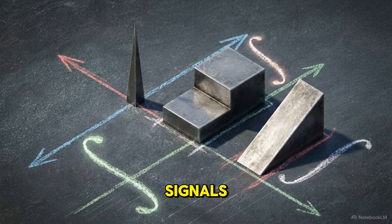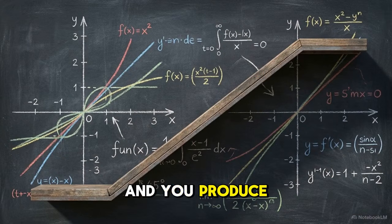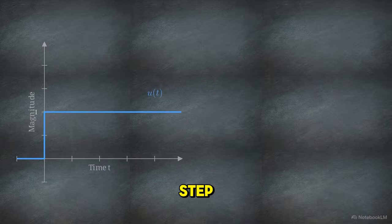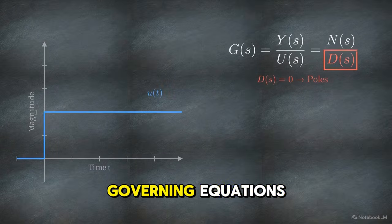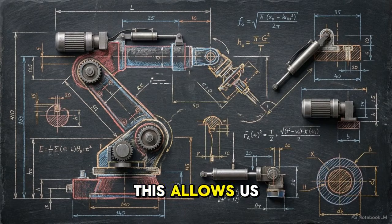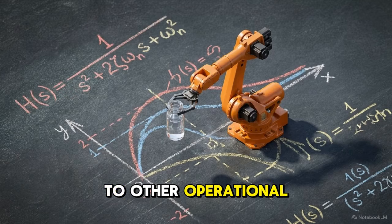These three test signals form a unified diagnostic suite tied together by calculus. Integrate an impulse and you get a step. Integrate the step and you produce a ramp. By analyzing how a system reacts to this sudden step, we can begin to derive the governing equations and root locations that dictate its performance. This allows us to build a model that predicts how that same system will respond to other operational demands.